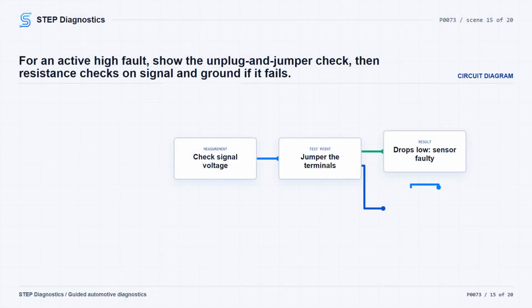Now, for the typical circuit high branch, disconnect the temp sensor harness connector and measure the temp sensor signal circuit voltage with the ignition on. The signal circuit voltage should be between 4.9 and 5.6 volts. With the fault active, jumper across the terminals and watch the scan tool. The temp sensor signal voltage should typically change to 0 volts with the jumper in place, or the circuit low fault should set with the jumper in place. If that happens, the sensor is faulty.